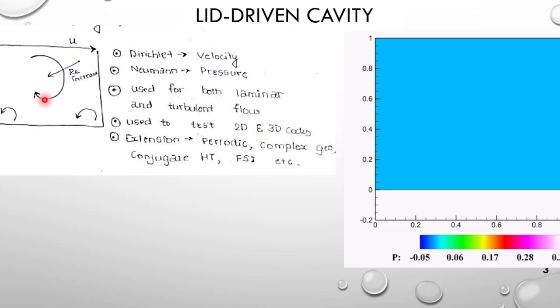So what happens is that, assume that the bottom plate is flexible in nature. Now due to the fluid flow, it imparts a stress on the bottom wall. This stress is mainly pressure stress and shear stress. This kind of oscillates the wall because it is flexible in nature. So it is a coupled problem, and due to the oscillation of the plate, there is a change in the flow pattern also.